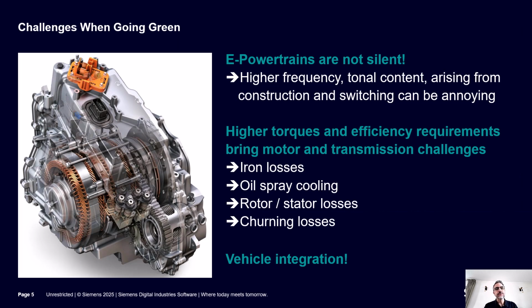Looking at the high-level challenges of edrive engineering, NVH comes as one of the first points in that electric drives are not silent and have very specific noise characteristics, higher frequencies due to the construction of the electric motor and the transmission, tonal content, and phenomena such as the switching frequencies from the inverter can be very annoying, despite the fact that the overall levels of the e-powertrain are limited compared to traditional powertrains.